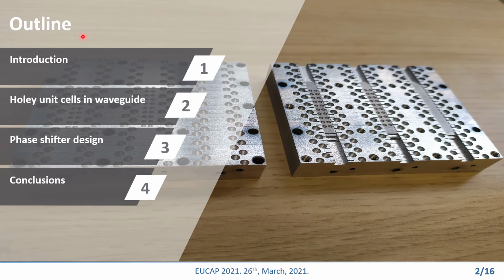Then, in the third point, we take advantage of the Glide-Symmetric Holey unit cells and the through-holes to design a reconfigurable phase shifter. The design is analyzed in CST and some results will be presented. Finally, the main conclusions of this work are commented in this last point.